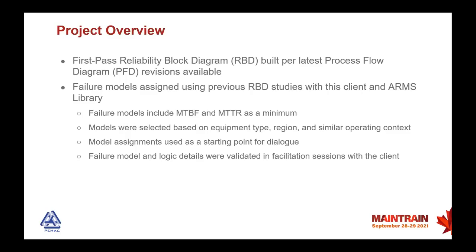The failure models themselves were assigned using previous reliability block diagram studies with this client and from ARMS' library. The failure models within the software include, at a minimum, mean time between failure and mean time to repair. Those models were selected based on equipment type, the region, and the similar operating context. Model assignments were used as a starting point for that dialogue instead of being taken as the gospel. And then failure model and logic details were validated in those facilitation sessions with the client.